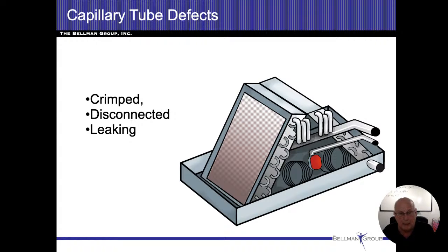So the outside cabinet and the size of the compressor and the size of the coils have to match the indoor refrigerant coils as well. They can't be like a 4-ton unit outside and a 2-ton unit inside. They must match. Otherwise, they're not going to work properly.